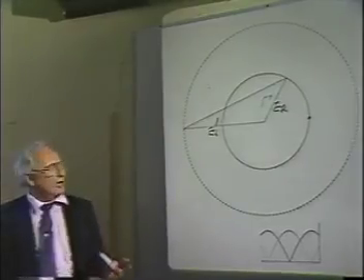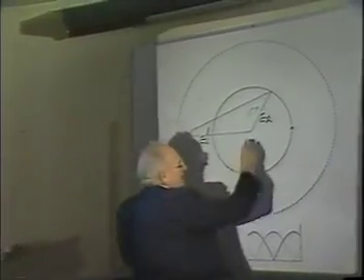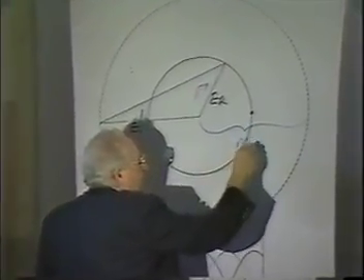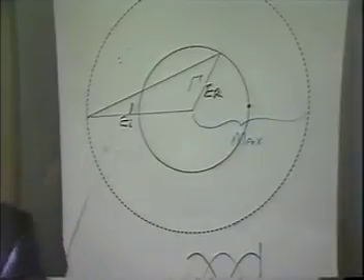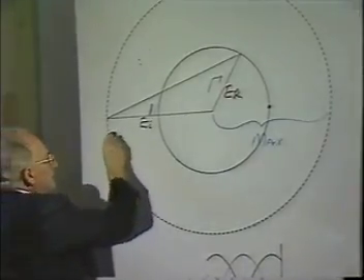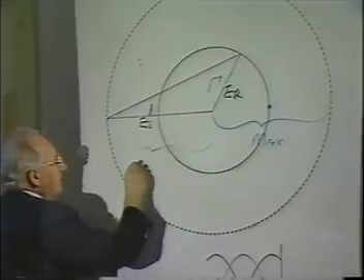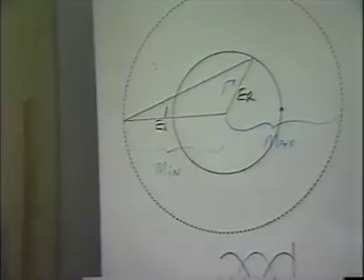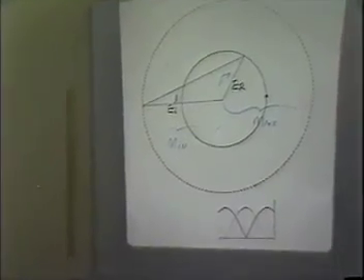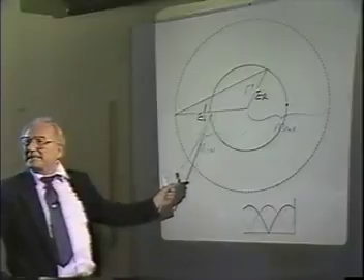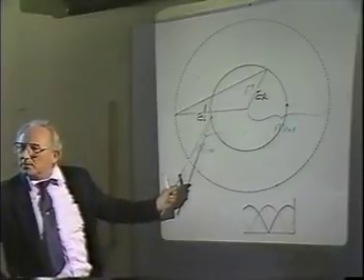One thing about this chart, everything on this, that's the maximum axis, isn't it? Everything on this side is the minimum axis. If you were talking about current on this chart, the current maximum would always be over here because the voltage minimum at the same point on the transmission line would be over here.